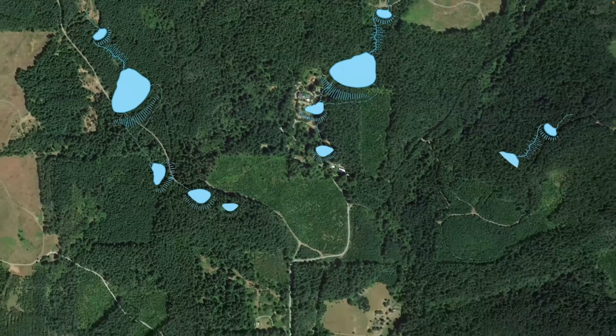You can run your pipe up and over into a screened intake in the pond, have it go up and over the dam and back down, and there are certain conditions you need to be able to create an adequate siphon with enough drop to really get that water moving well and into the pipeline. The siphon can be primed simply by filling a 5-gallon bucket and pouring it into a T at the top of the pipe from the dam. So that's a nice sort of low-tech way of priming the pipe.